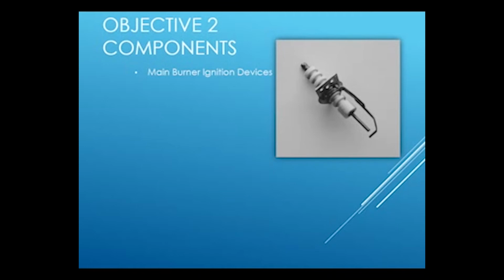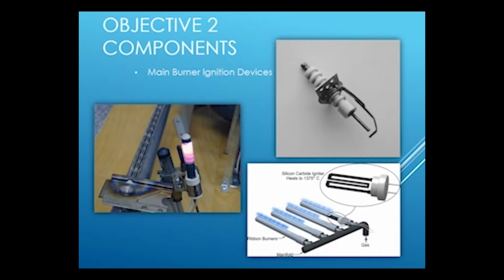A lot of systems require a standing pilot flame that will have either a direct spark or an electronic ignition, which means that we need high voltage transformers and wiring. We can also use a hot surface ignition system, which would require 120 volts.